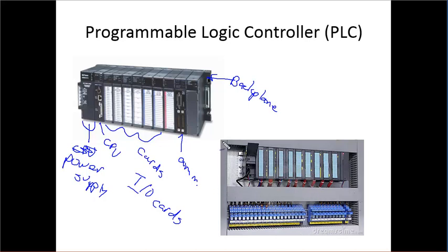And then this right here is called Panduit, and it's actually kind of neat, but it's just to hide the wires and make it all look neat so that you don't just have a jumble of wires when you open up a cabinet. It keeps you from snagging the wires when you're working in there. Not only does it look nicer, but it's functional. This Panduit, the cover just pops off right here, and then you can see all the wires in there. And on the side, it's got these little fingers, so you can feed the wires out through it.